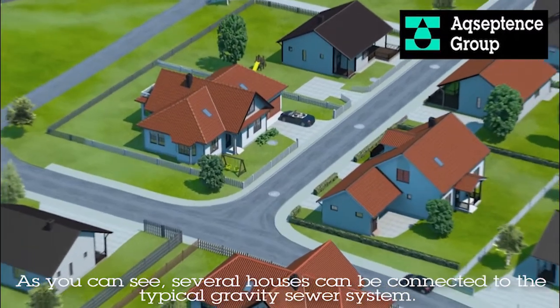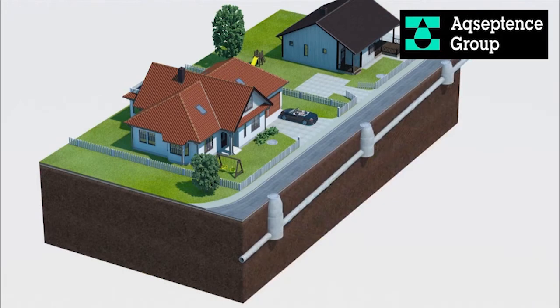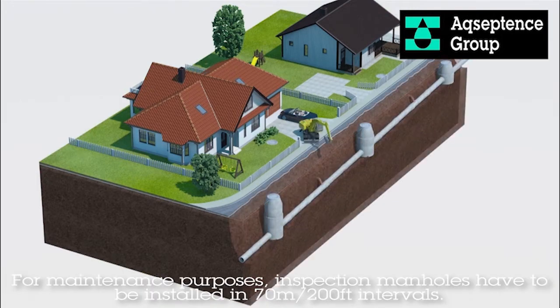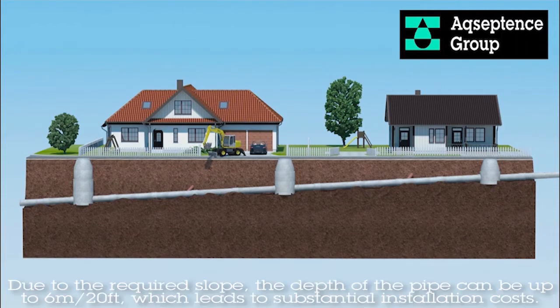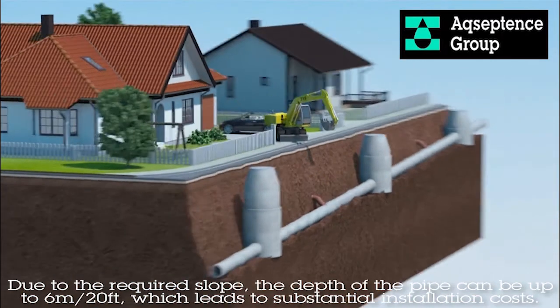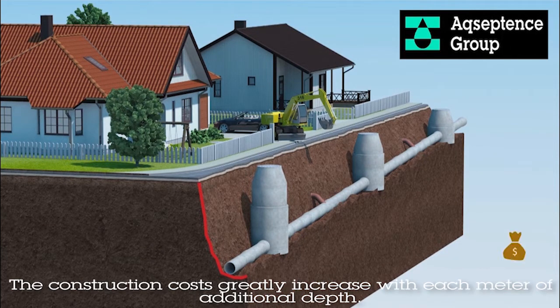As you can see, several houses can be connected to the typical gravity sewer system. For maintenance purposes, inspection manholes have to be installed in 70-meter or 200-foot intervals. Additionally, each change of slope or direction requires a change of the nominal width, the material, junctions, and an inspection chamber. Due to the required slope, the depth of the pipe can be up to 6 meters or 20 feet, which leads to substantial installation costs. The construction costs greatly increase with each meter of additional depth.